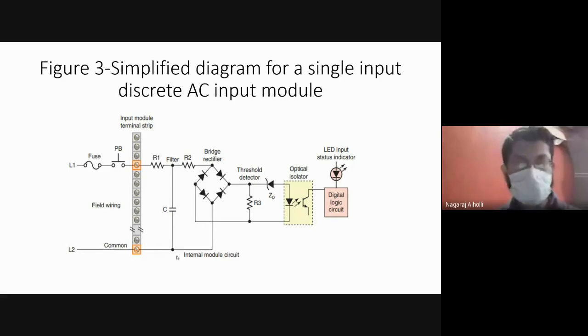When C value is very less, almost 0, Xc will be infinite, so the current will be 0. It is an open circuit. Based on this property, it will try to remove the noise signal present in the input signal coming to the filter section.